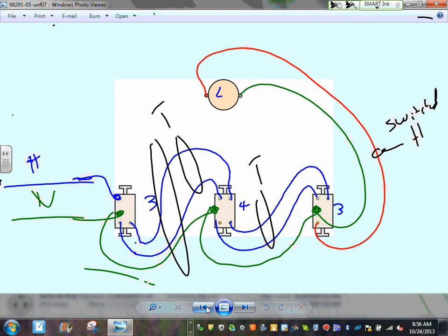Now, all you need to do is go to Karen's lab and grab whichever wiring method you want. MC cable, grab the MC cable, tie it to each one of them. EMT conduit, no problem. Make sure you have the right fittings. Of course, the devil is in the detail, because if you have EMT and you don't know which type of fittings to use, it becomes a matter of material knowledge. Any comments, any questions? Can you guys assure me that you're going to wire these? If you have any question, ask me. But I would like you guys to sketch them.